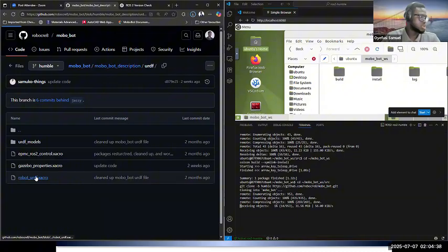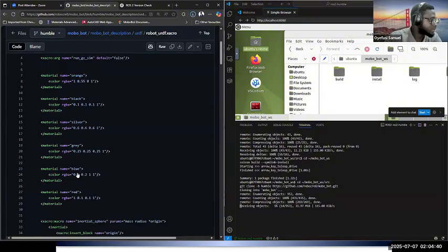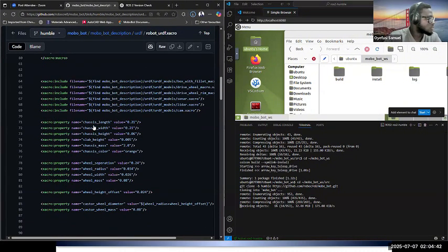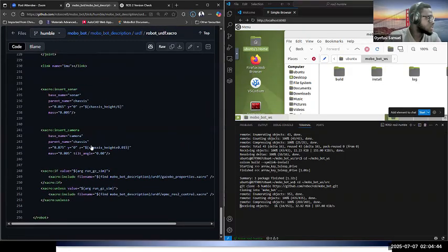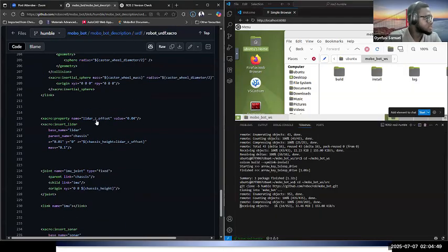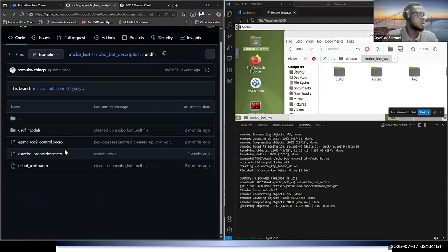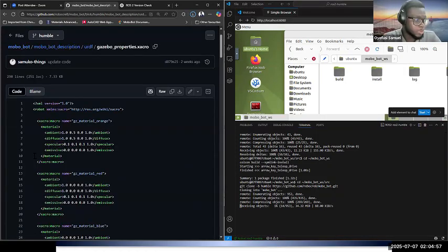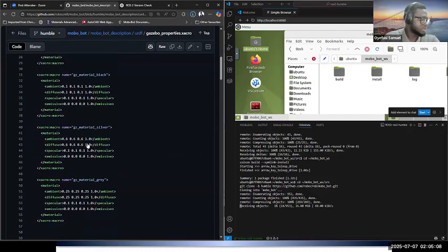In the robot description you see the links, the materials, and the Xacro, which includes the different sensors, like camera and sonar, plus the joints and links. This is where all the links and joints of the robot are described. In ROS, most of the files you use in building projects are Xacro files, which is why you see the robot XML and Xacro, basically describing the environment.